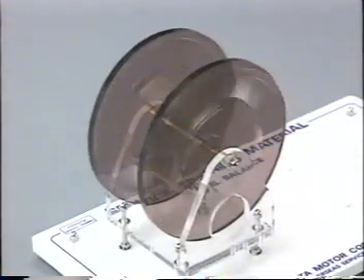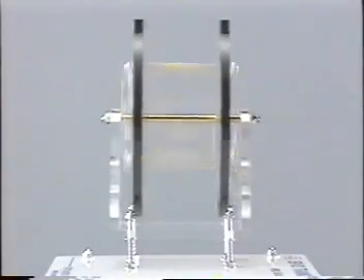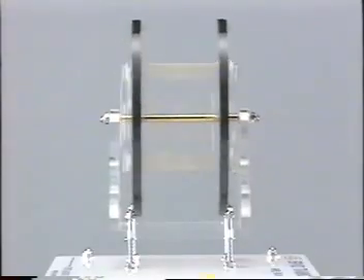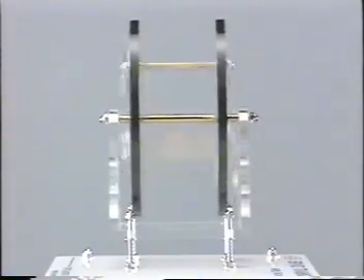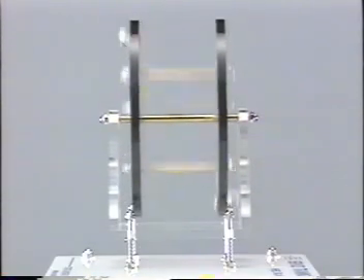On the contrary, when the disc assembly is turned, the points where the centrifugal force acts on the heavy spots are different, so vibration is generated as a result. A wheel in this condition is dynamically unbalanced.